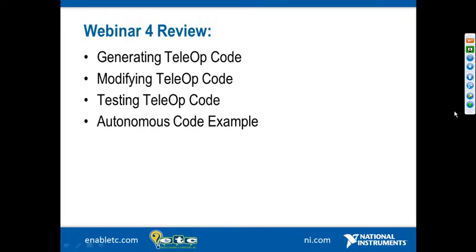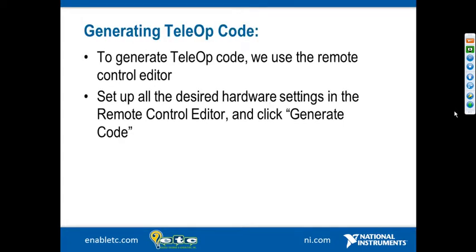To begin with, let's start with a very short review of what we covered last week in webinar number 4. In that webinar, we went into a lot more detail about how to create and modify both teleop and autonomous code, as well as a little bit of detail as to how to test and run our teleop code. We reviewed how to generate teleop code. We can use the remote control editor within LabVIEW to automatically create our teleop code as a starting point. We saw how it's important to set up all the desired hardware settings in the remote control editor, and then simply clicking Generate Code will create our teleop VI.